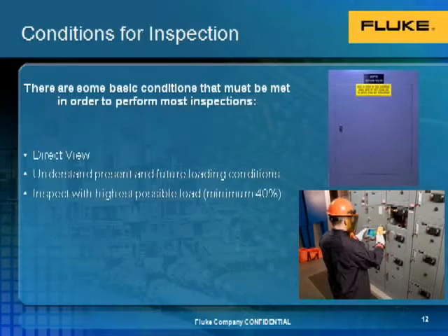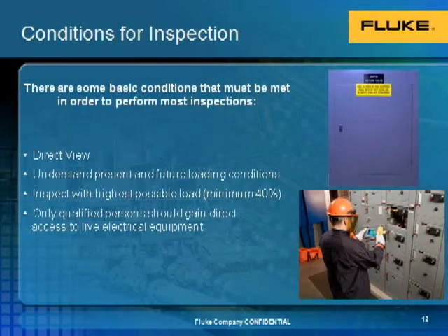Try and inspect with the highest possible load, the minimum being 40%. Make sure that you're not inspecting a piece of equipment that just turned on a minute ago. Only qualified persons should gain direct access to live electrical equipment. Be sure to follow the NFPA 70E and OSHA regulations and requirements, and always wear PPE, or personal protective equipment.